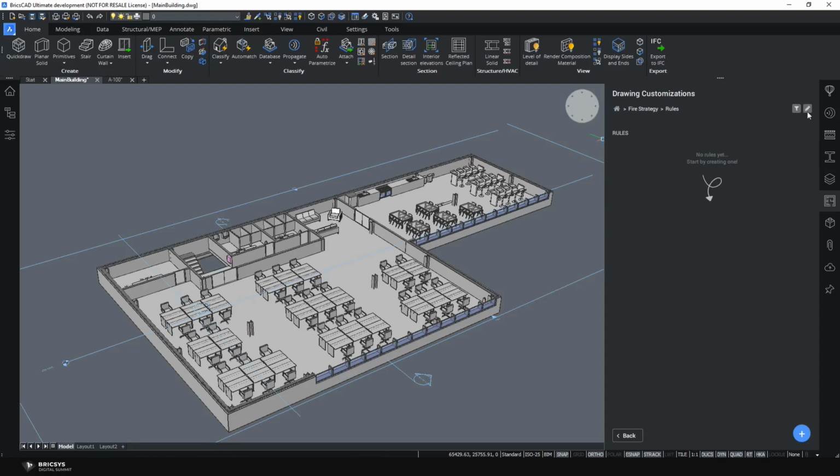So let us start by creating an entity customization. Here I will add a style. I want to start by showing you how to define a style. So I click Style. I click again the same plus icon as we used before to generate a new customization. I now select it to create a new style. And the first one can be, for example, red continuous. In this case, I'm giving my style literally the name of how the representation should look in the end, a red continuous line.